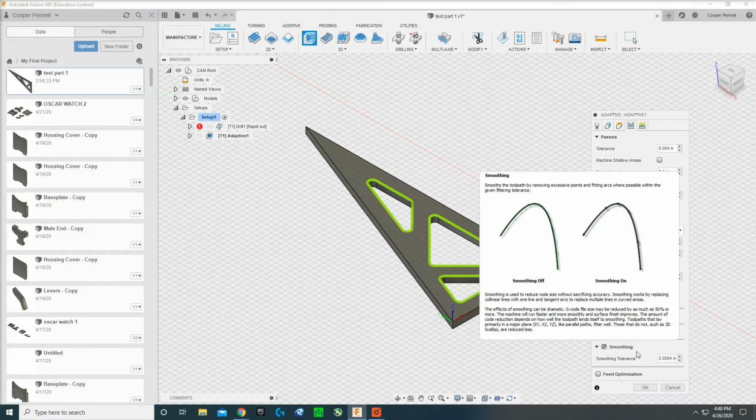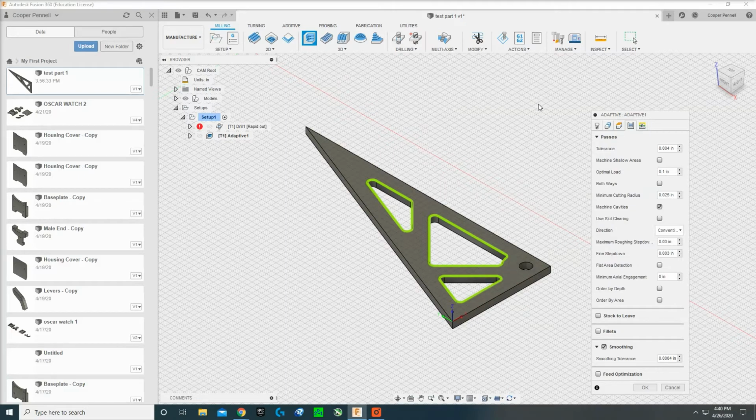However, if you have smoothing turned on, it alters what they call the G-code. The G-code is those commands. Like a G-code line would be G0, G1, or G2. It's lines of code that tell the machine where to go, kind of like coding autonomous, honestly. And so there are different types of G-code. There's basic G-code, like X and Y. So X1, Y1 would be the basic kind of G0 G-code.